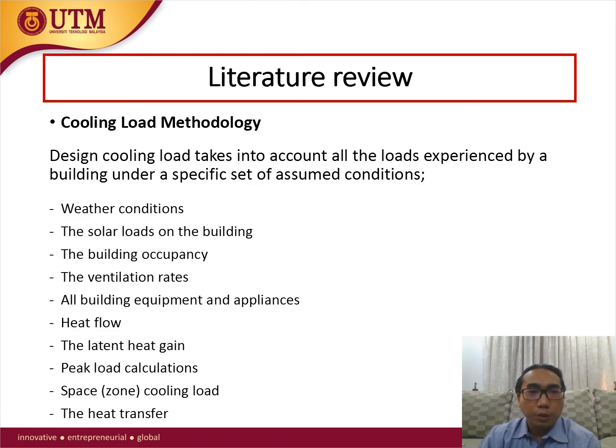Cooling load methodology. Design cooling load takes into account all the loads experienced by a building under a specific set of assumed conditions. Weather conditions are selected from a long-term statistical database. The conditions will not necessarily represent any actual year, but are representative of the location of the building. ASHRAE has tabulated such data.